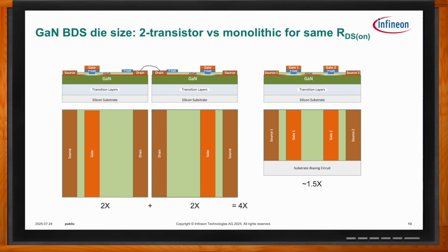And here's why. If I look at traditional MOSFET, silicon carbide, or IGBT, they all have vertical current flow. The drain is on the bottom. So in order to do a bidirectional switch with any other topology, I now need to figure out how to pattern transistors on both sides of a die and line those up within a couple of microns, submicrons. Very, very challenging. Never say never. Maybe that'll happen someday in the future, but right now, there's nothing else that can create such a small bidirectional switch as GaN. Sure. So are these real devices that are being used today?